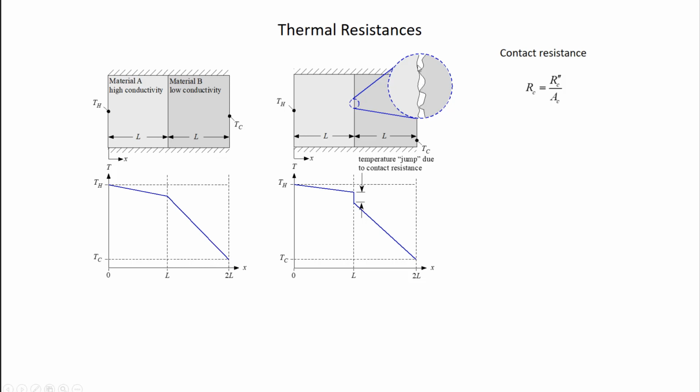Did you fill this gap here with something semi-conductive so that it's a little bit easier for the heat to get across it, right? So all those empirical parameters will go into what's the actual contact resistance here. When you make these contacts, for example, at cryogenic temperatures, oftentimes you'll actually fill the gap with something like indium that's a very soft metal and can squeeze and take up some of these spaces to make it an easier transfer of energy across the gap.